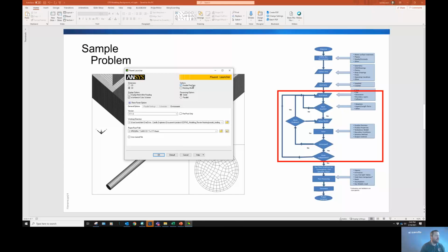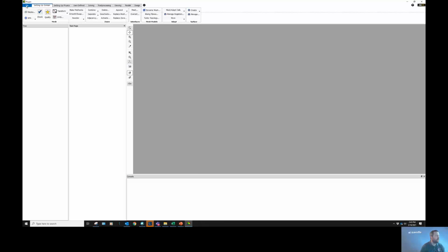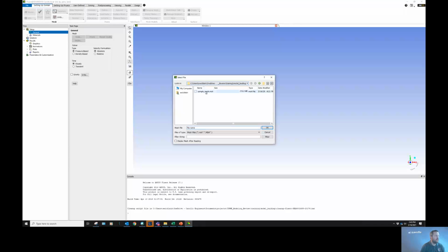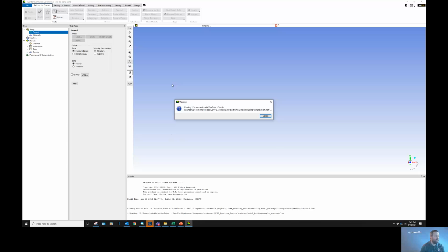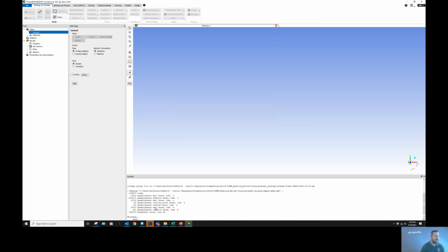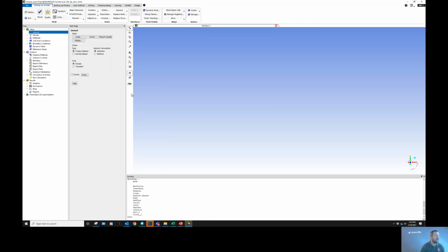So we're going to open Fluent, make sure we're in double precision. Other solvers have similar startup procedures, make sure we're in 3 dimensions. We'll open the software, read our mesh that we wrote out in the last step. In the console window, you get some information. Again, most of the software is similar, provides information, a summary, and other parts of the model. There are tools here that you can use for mesh checking. We will need to scale it.